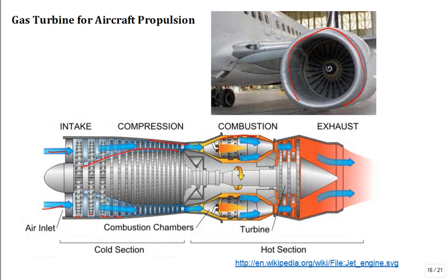Most of it doesn't go right into where the fuel is, but goes around it. But you have a combustor, and in that combustion chamber, it's mixed with the other gases because it's so hot, so high temperature. And the key thing is the metallurgy in that first turbine stage. You can't have it so hot that it'll damage your blades and they'll fail.